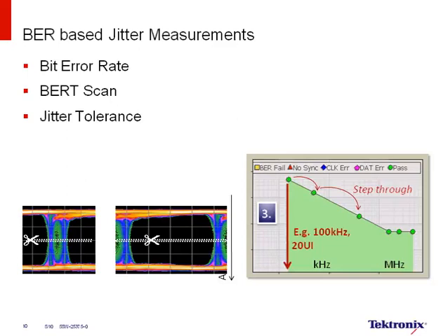A simplistic way to stress receiver testing is by varying the frequency and amplitude. However, in the real world, there are jitter stressors caused by, for example, your channel. Earlier, we spoke about jitter decomposition, or looking at how the different jitter is broken down into their various categories.